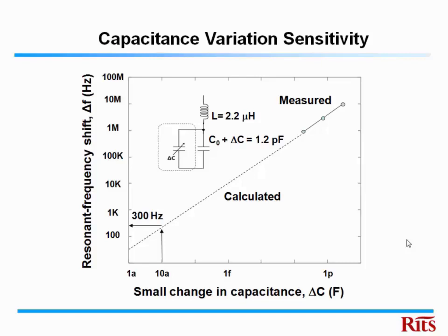But in this case we use 98 MHz as the oscillation frequency, and we need 100 Hz order accuracy or resolution. We can count that using, for instance, an instrument type frequency counter, but it's very expensive and not handy for the system. So we need some solution here.